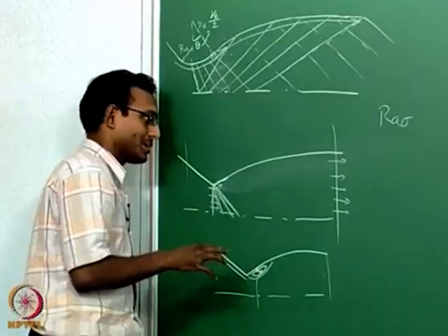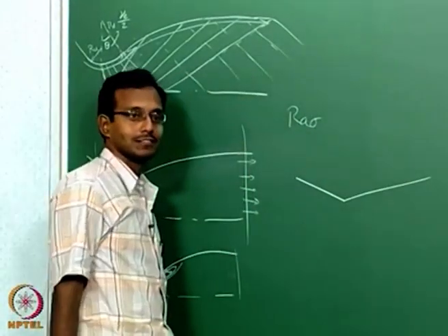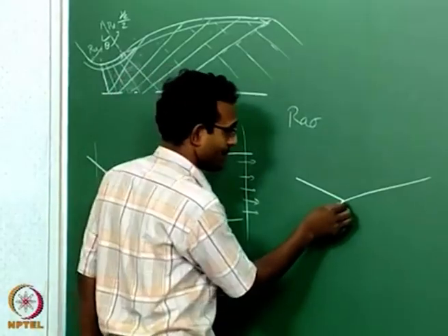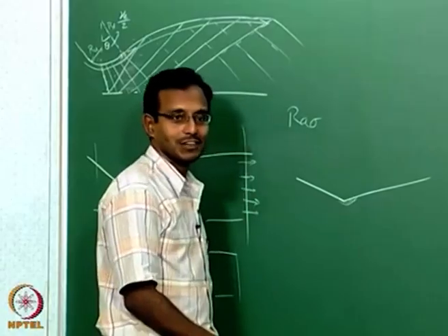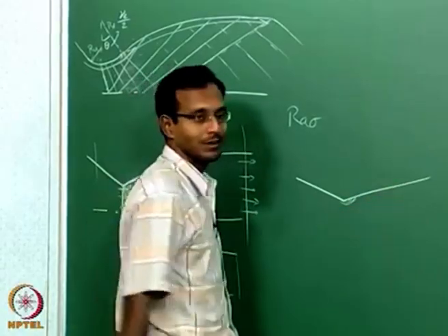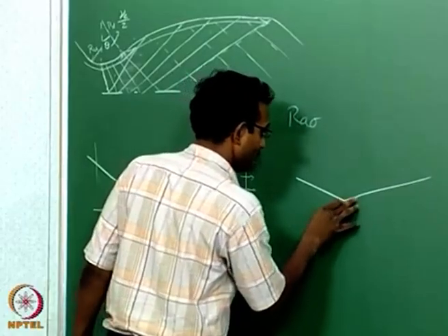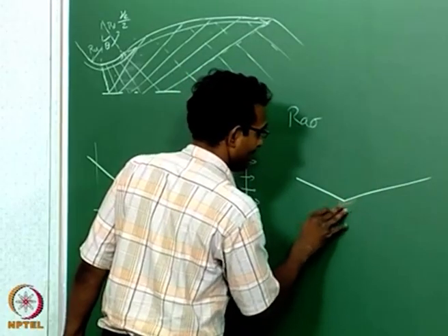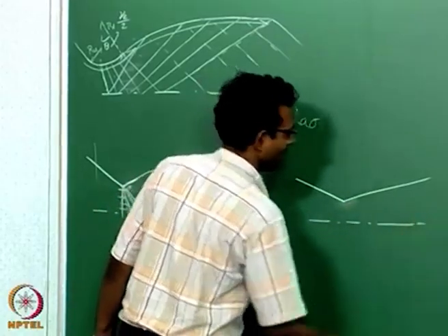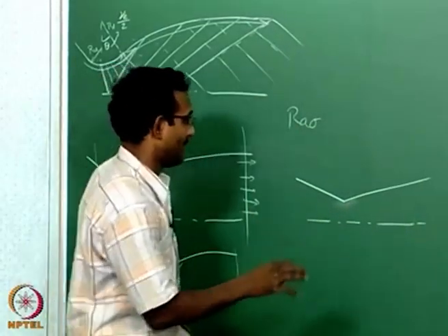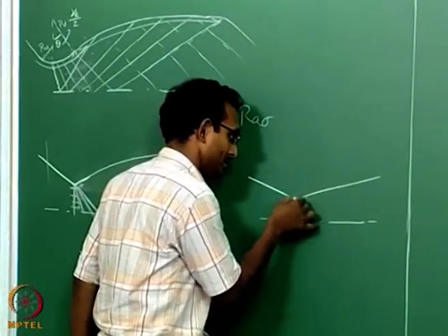As of now, we will study a case where I have a straight line nozzle like this. Of course, if I make a nozzle like this in real life, it is going to have a small bump here and a recirculation there. So it will not give me the correct and steady Mach number. I will just assume that those things do not exist. Viscosity never exists in real life, I will assume, which is really absurd. Anyway, I will go about doing calculations with point expansion here.